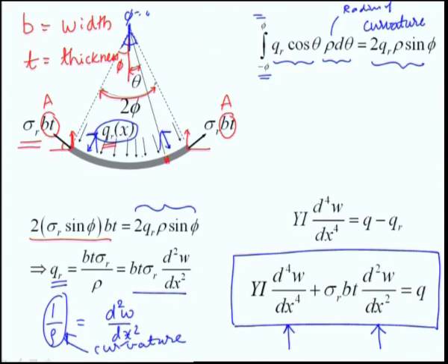And now, in our derivation we took a small element here. So, we did not make any assumption about stress being uniform throughout the beam. Now, if it were to be changing as well, you can put this sigma r as a function of x. So, the sigma r here can also be a function of x. Residual stress can vary along the axis of the beam, and you can take this into account. This is the new governing equation that we need to solve compared to previous cases where this second term was not existent.